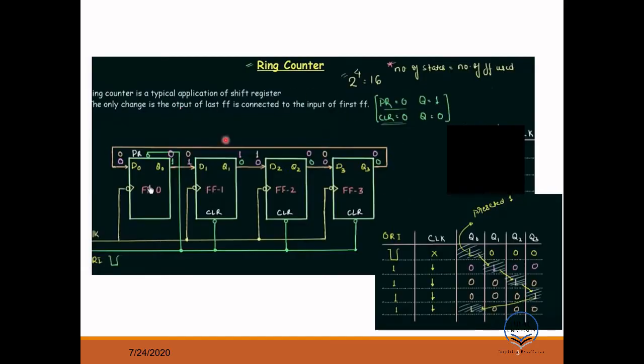So you already discussed this, but I want to emphasize this truth table. Okay, say your override is low, so low means override is activated, right? So if override is activated, this is taking charge, so it doesn't matter what the clock is, right? It is getting the priority because this is an asynchronous action. So if it is getting the priority, then what will happen?